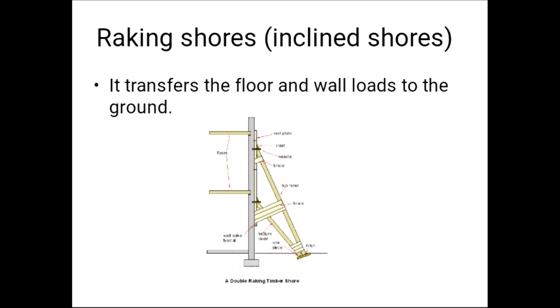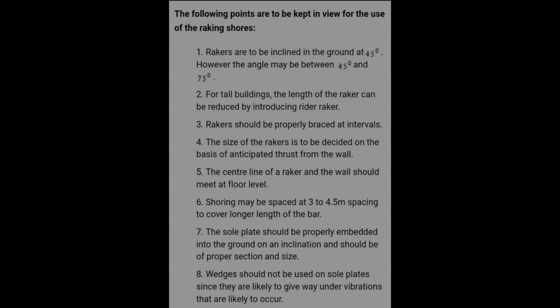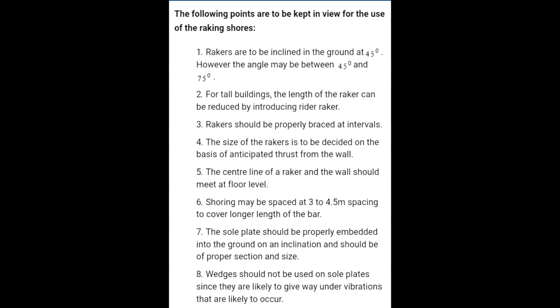So this is the raking shore. It is an inclined shoring. The following points are to be kept in view for the use of raking shores. Rakers are to be inclined to the ground at 45 degrees. However, the angle may be between 45 degrees and 75 degrees.